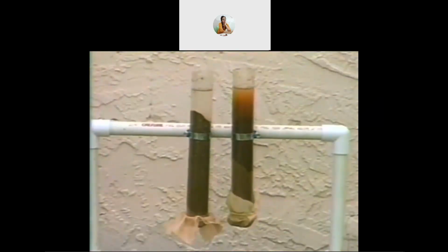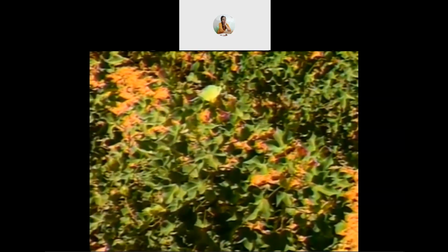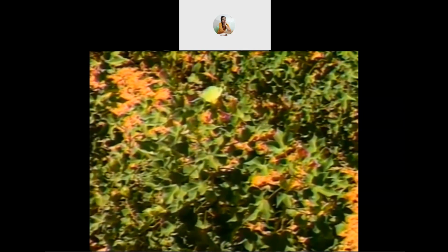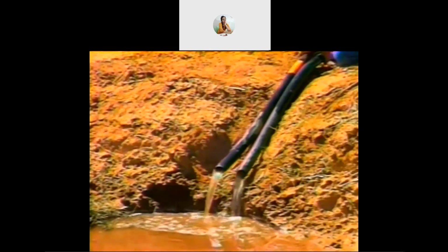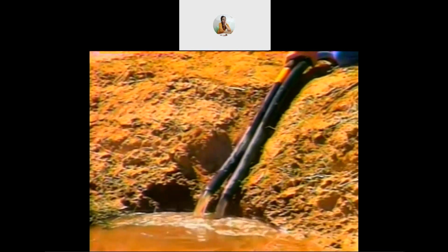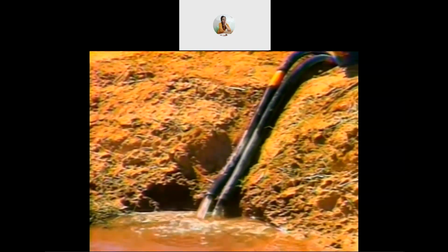The soil type. Is it a light soil with a lot of sand, or a heavy soil with more clay? Water will enter a light sandy soil much more quickly than it will enter a heavy soil. Does the soil type change in some parts of the field? For example, some fields will have bands or fingers of sandy soil over part of the field. Plants growing in sandy soils will look stressed earlier than in other parts of the field because the sandy soil holds less water. You will probably need to increase the flow rate to rows that have sandy spots so that the water will make it to the end of the row.